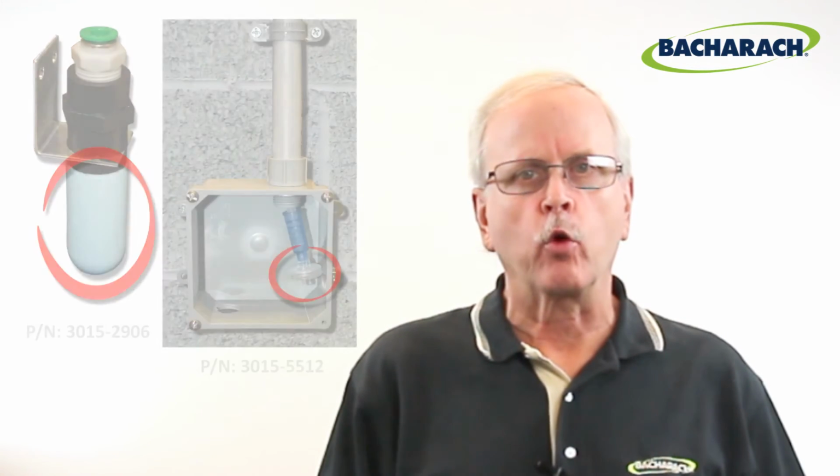Troubleshooting the clogged or pinched sample tube may be a little more involved. This may be as simple as locating then removing a kink or replacing a small section of sample tubing, or as complex as running all new sample tubing if the obstruction cannot be found or cleared.